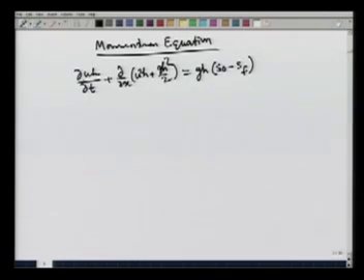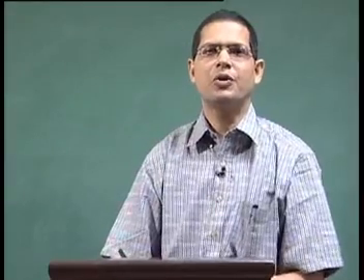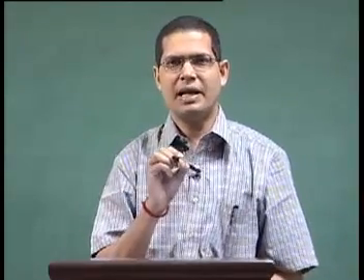Coming to the different terms in these equations, as we said earlier, u and h are respectively the flow velocity and flow depth. Here g is the acceleration due to gravity, S naught is the bed slope, and as we are assuming one dimensional flow, S naught or the bed slope will be the slope along the flow.